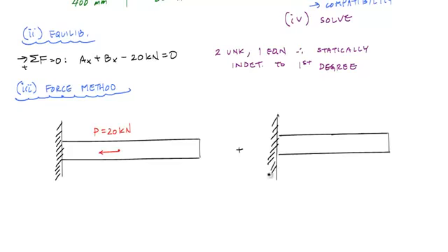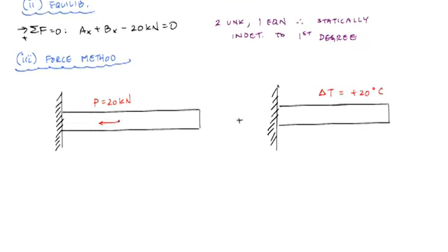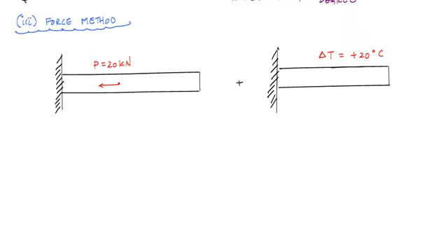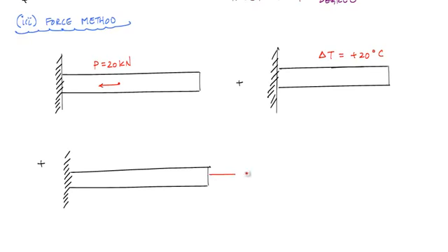I have the same structure with only the temperature change applied to it. These are my primary loading drawings, essentially statically determinate with the redundant removed and the loads applied to it. And then now I have my redundant loading, which is adding back that reaction at B. And I apply that loading back at B the way I initially drew it in my big free body diagram.